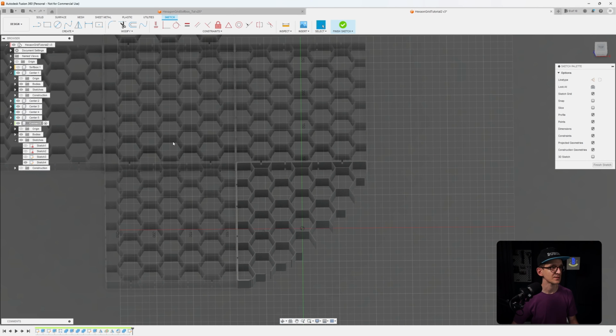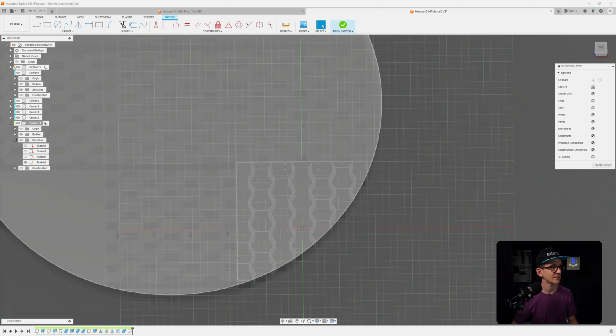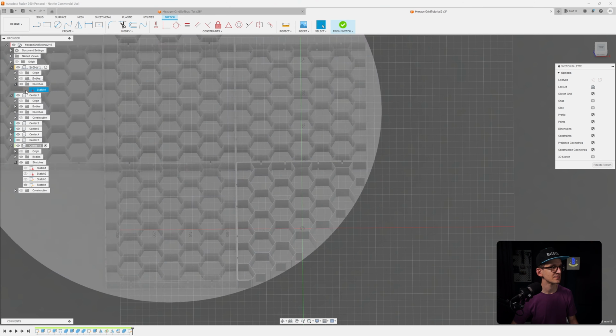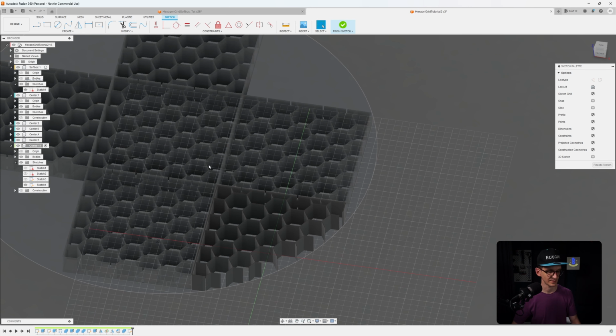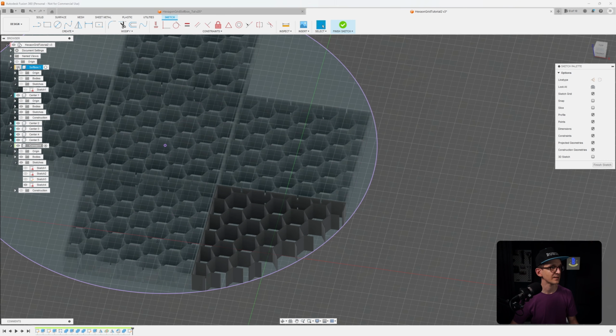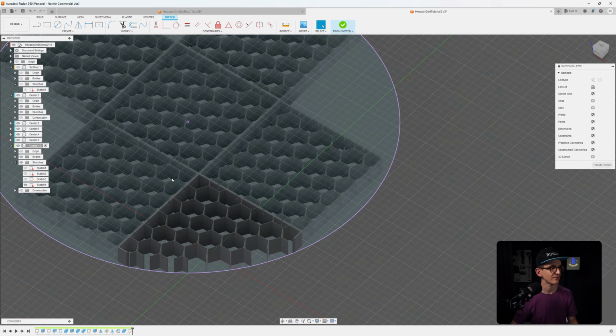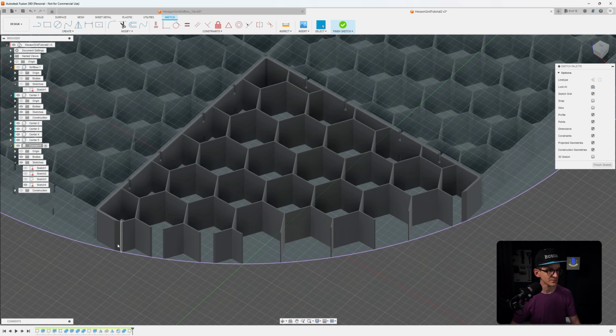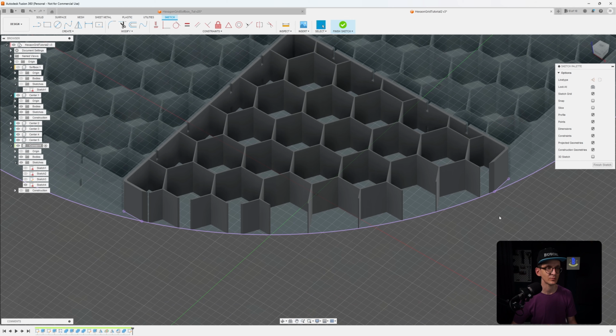What we can now do is actually enable the softbox again, but maybe disable the body, but still have the sketch. And now we can reference on this sketch that we're currently working, the outline of the softbox itself. That's going to be enough. We can disable it again, but we still have now the outline here in this sketch. We can actually use it. We can also project those lines where the current cutout ends. And now we have actually everything we want.